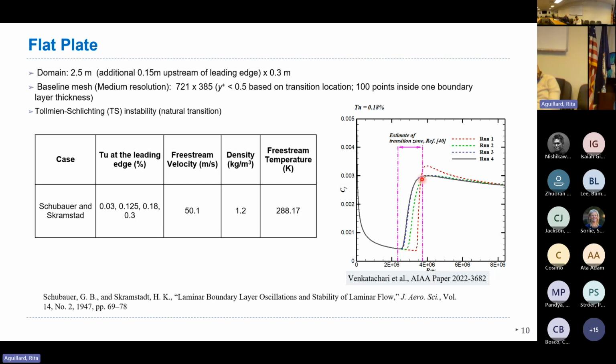LASTRAC tells me the transition location. The way we do that is, for each disturbance level there's a correlation called the max correlation, which will tie that to a particular N factor. You can use that to determine what N corresponds to transition, or for each facility, people have come up with certain N factors which you can use. So through that, it tells me transition should actually happen at say 2 point some million. We have an under relaxation parameter to make the process more robust and not noisy. So we won't directly update the solution with 2, but we would use an under relaxation to put it somewhere in between in the next iteration, and then iterate. Within 2-3 iterations, in many cases, we get the converged solution, and we get a good prediction of the transition behavior, like where transition onset happens, where transition ends, and so on.